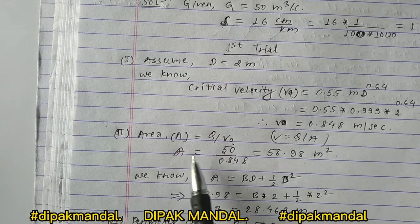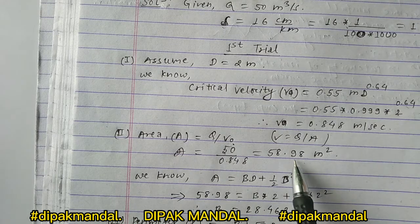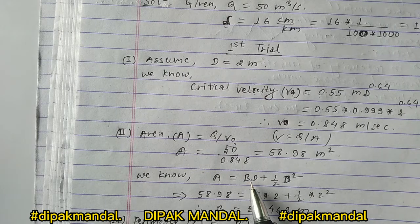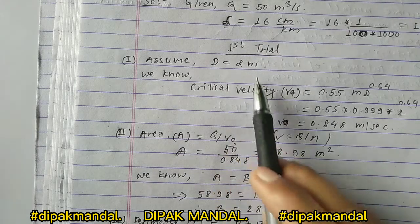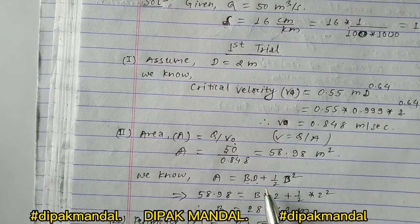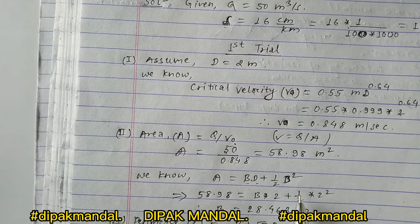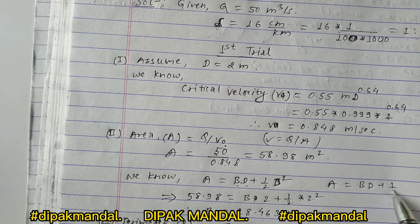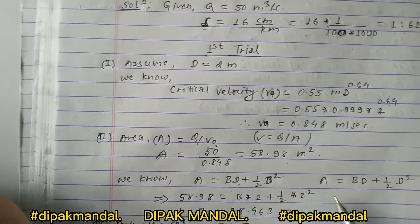We have calculated the area equal to 58.98, but the value of B is unknown. For calculating area we use both B and D. We already assumed the value of D as 2 meter, but we do not know the value of B, so we have to calculate B with the help of this area. As we know, for an irrigation canal the area equals BD plus half D square. We have to know this formula.